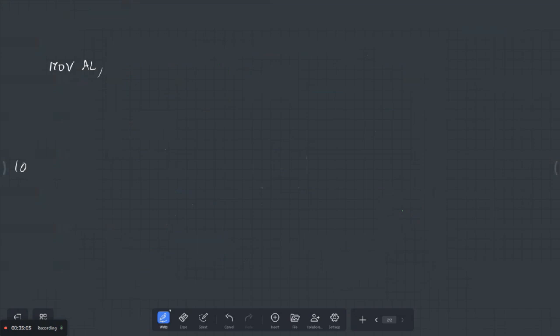Suppose if you want to give 10000000, what is the data you should give? 80H, right? So MOV AL, comma 80H. Now you do OUT 9CH, comma AL. What will happen now? Okay, right?